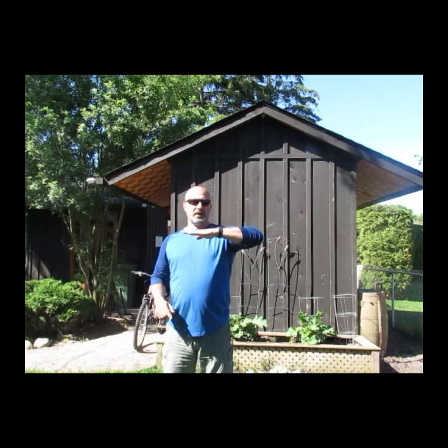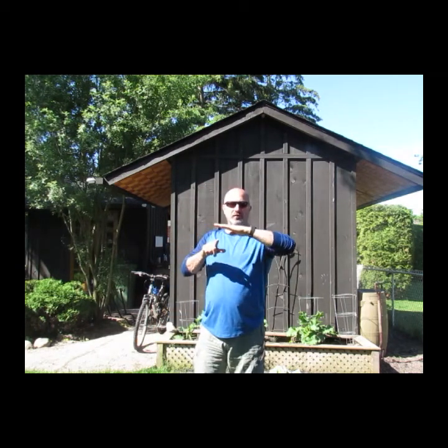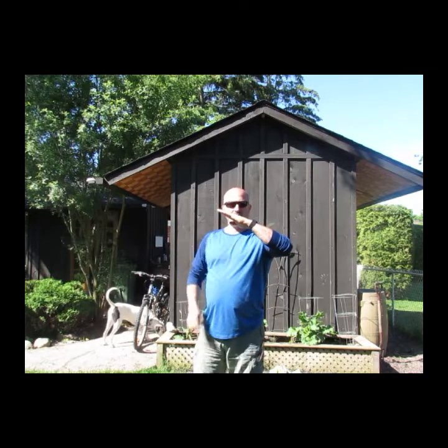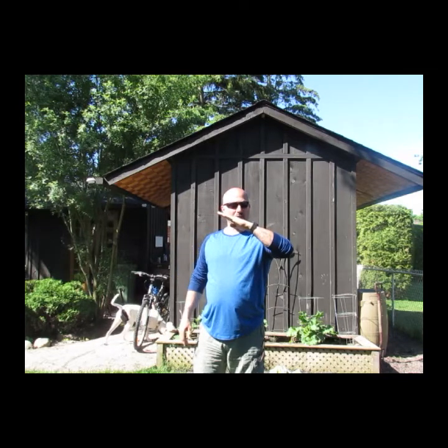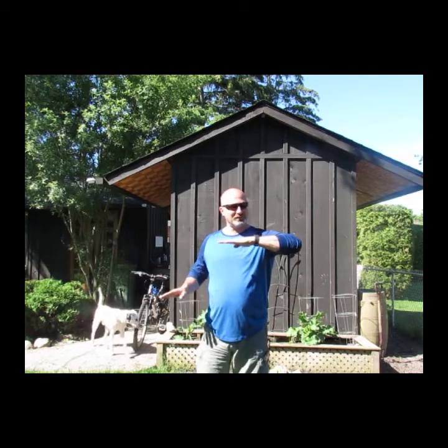So you can see that if I rise up 1 inch, just estimating, for every 12 inches across, then you've got a very low pitch. If I rise up 4 inches for every 12 inches across, now we're starting to get a little bit more steep. And remember that the steeper a roof, the easier it is for water and snow to melt and run off. You want that. A flat roof is a totally different situation.